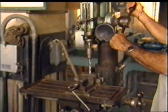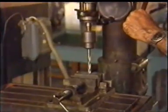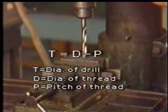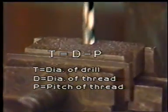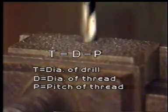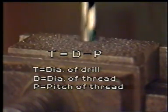Before cutting threads, a hole of appropriate size is drilled in the job. The approximate size of the hole is given by the relation T is equal to D minus P, where T is the diameter of the drill, D is the diameter of the thread, and P is the pitch.